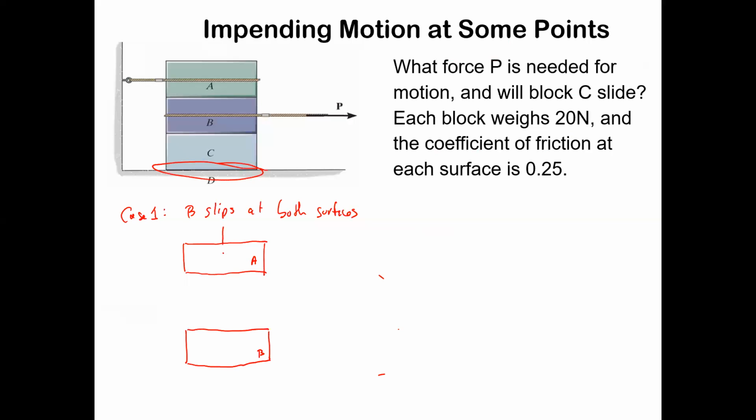So we have a weight force, the force of gravity, acting in the middle of that box. And what else is acting on that? Tension. Yep, we can say there's a tension at A. There's not a rope there, it's just a force. That's all that thing is feeling. That's what happens when you make a free body diagram. And what else is acting on it? Normal force. And this normal force is at the boundary of A and B, so we can call it N_AB to distinguish it from other normal forces we might run into.